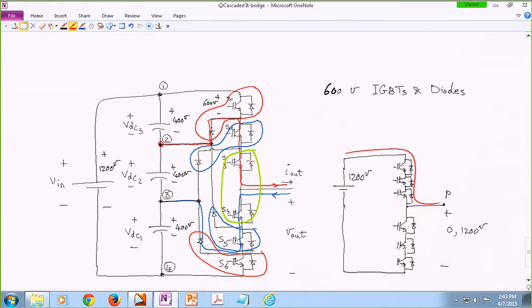we have to turn these transistors on at the same time, which is quite challenging because our gate drivers may have slight differences in terms of their time delay. The switch, even though they are coming from the same manufacturer, one of them might be reacting 2 nanoseconds faster than the other. As soon as one of them is on, assume that, for instance, this transistor is on, but the other 2 haven't had a chance to turn on. So the other 2 are basically bearing 1200 volts, which is getting scary.